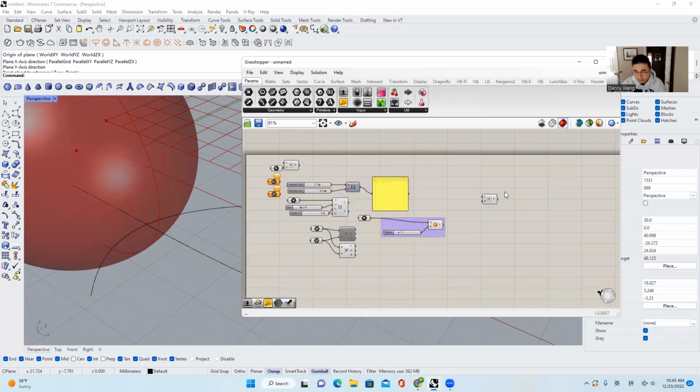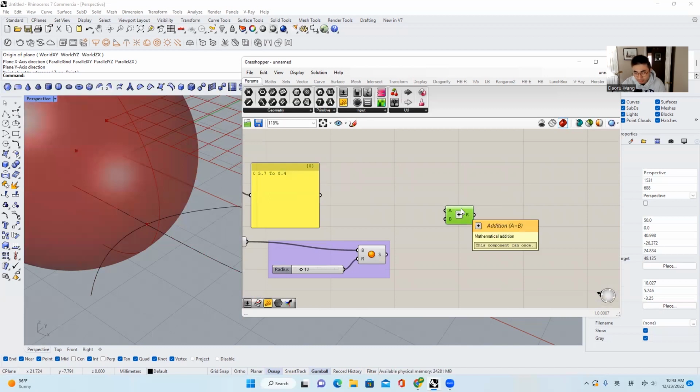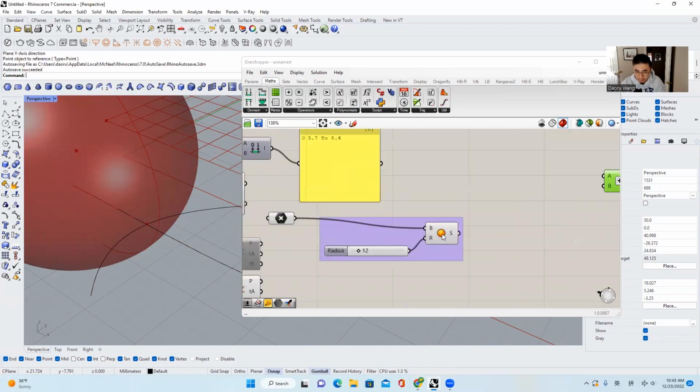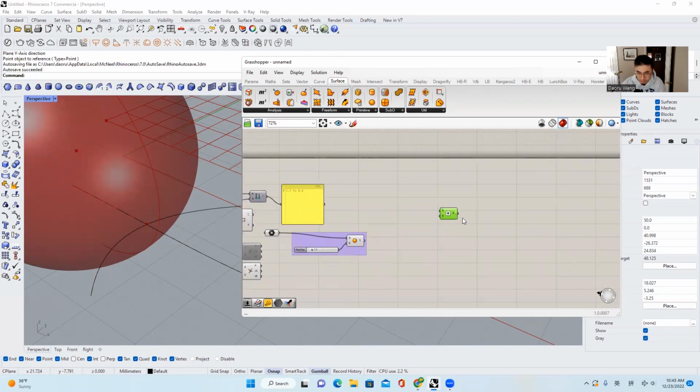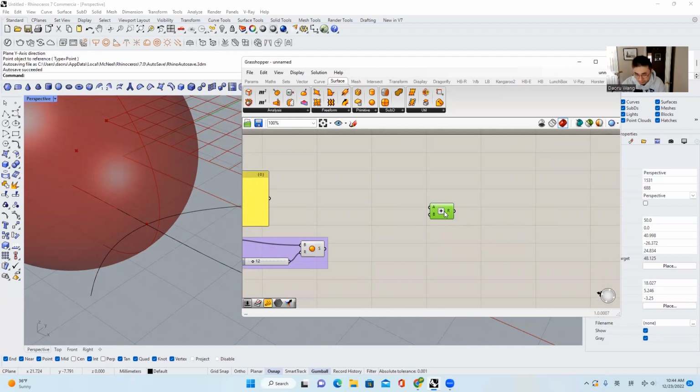And also if you find another file that you made before, or you find it from other people and you want to know where this specific component is, for example this one, I hold Control and Alt at the same time and I click it, it will show me where it is. Okay, and also about Alt, you can hold Alt and then drag left and right to give you some more space. Also, if you select this specific component first and then hold Alt, you can drag it around by copying it, right? The order does matter.